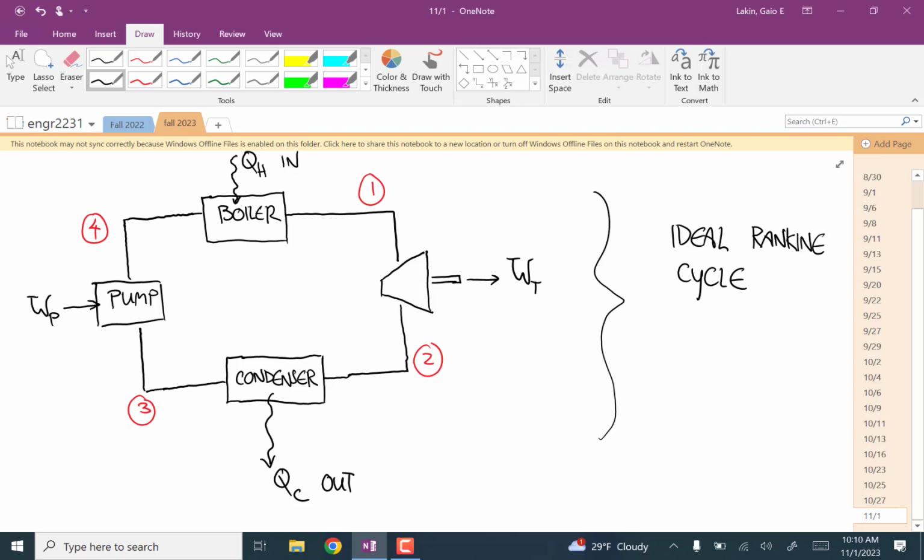if you have constant pressure and you start with a saturated liquid, and then you boil it to get a saturated vapor, you get this huge increase in internal energy without any corresponding temperature increase. A temperature increase would make it harder to keep pouring energy into this or pulling energy out of it.